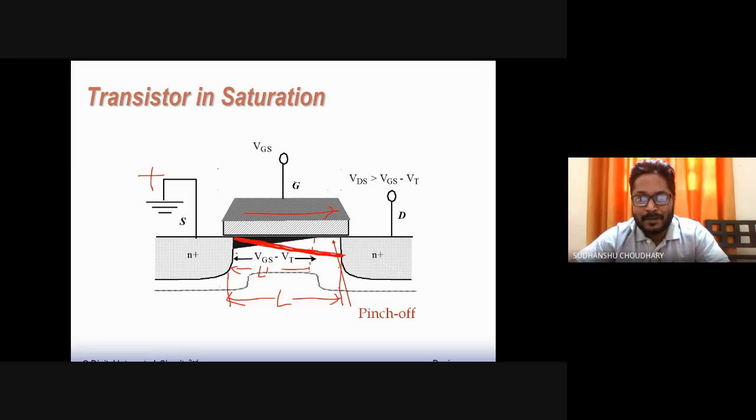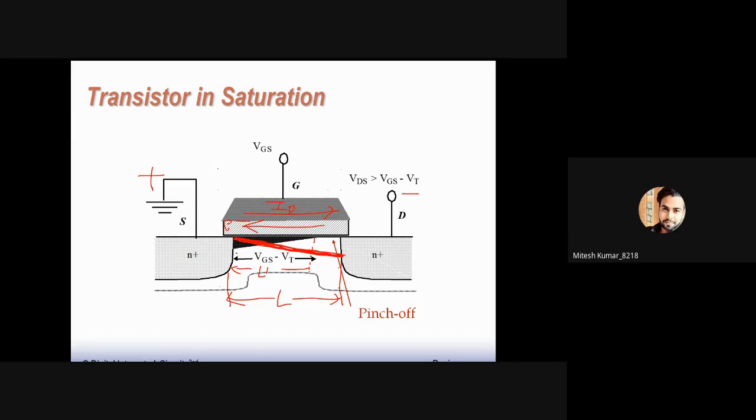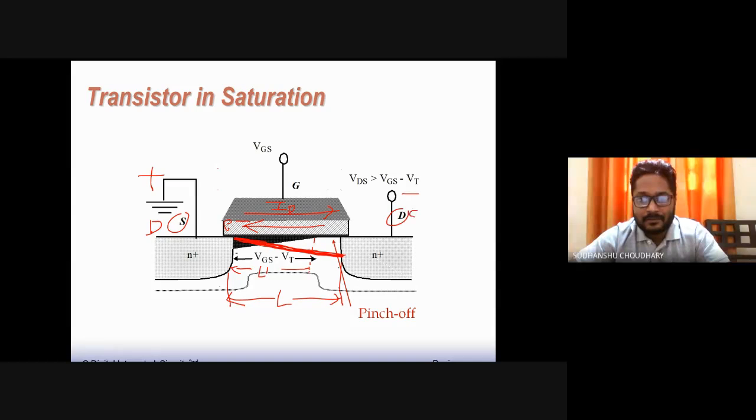When you are making this positive and this negative, the current will be from source to drain, and the electrons will move from drain to source. So we now call this terminal source and the other drain? Yes. Source means obviously a source of carriers, right? So in a MOSFET, you can interchange these two terminals.